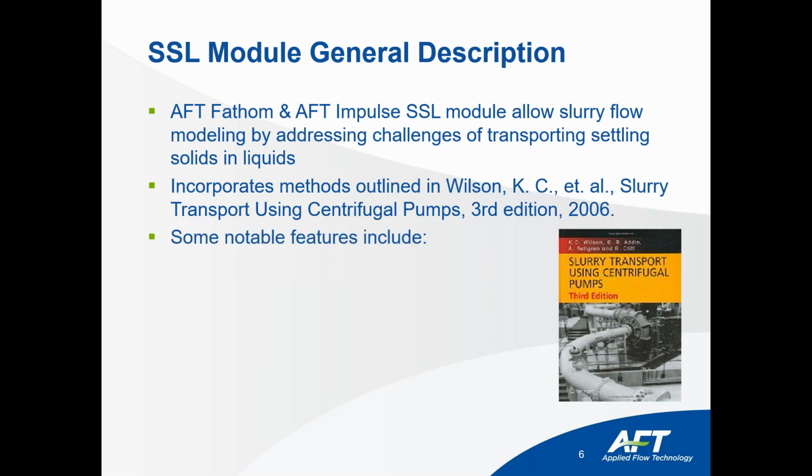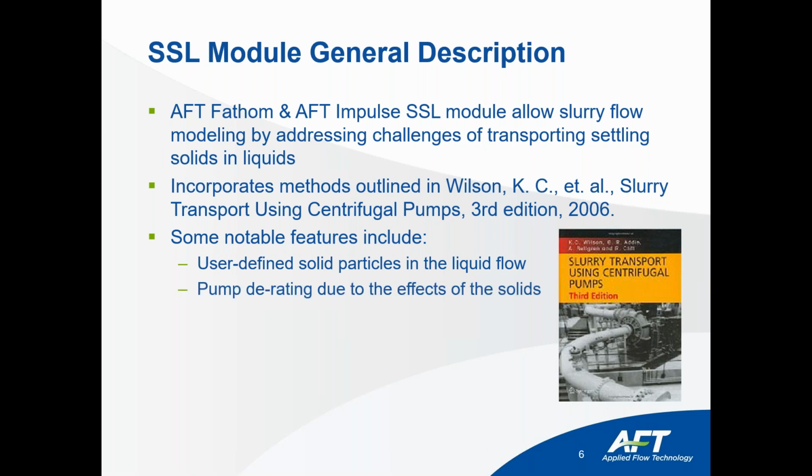Some various features that are really helpful is you have the ability to define your own type of solids in the fluid that you're trying to pump. You can actually account for the pump derating factors when you're trying to pump slurries. And we use the various standards, and I'll show you that here in a little bit, for calculating those pump derating factors.